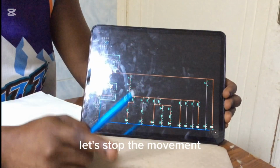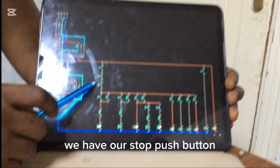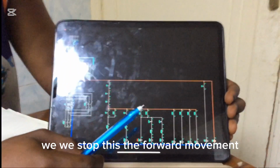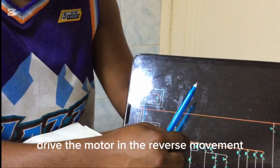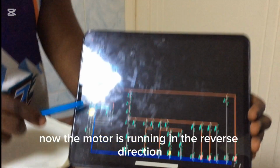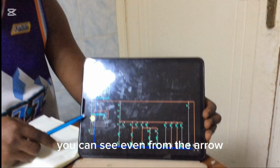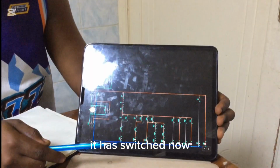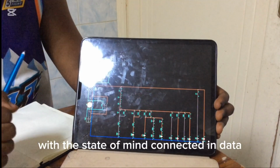Let's stop the movement. Now we have our emergency stop push button, we have our stop push button. We will stop the forward movement. Now let's drive in the reverse movement. Drive the motor in the reverse movement and see. Now the motor is running in the reverse direction. You can see, even from the arrow on the motor, with the stator winding connected in star, it has switched. Now it's still running in the reverse direction with the stator winding connected in delta.